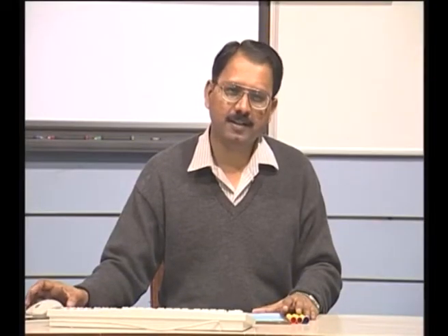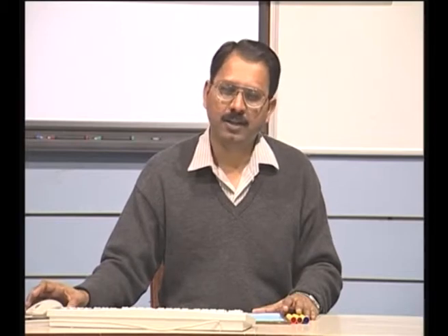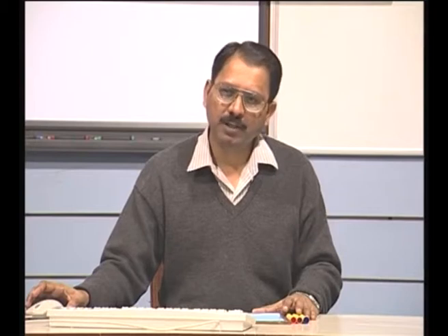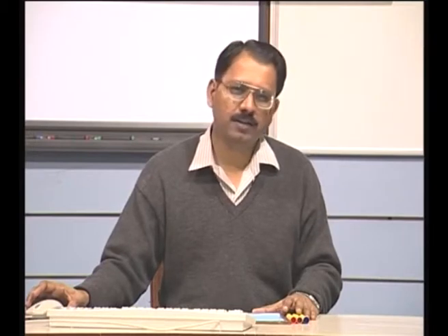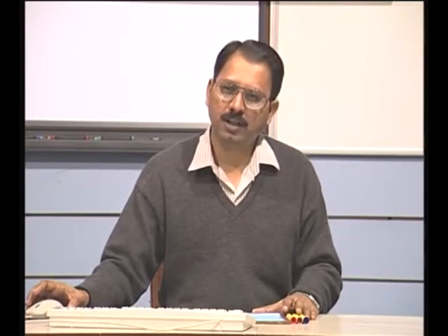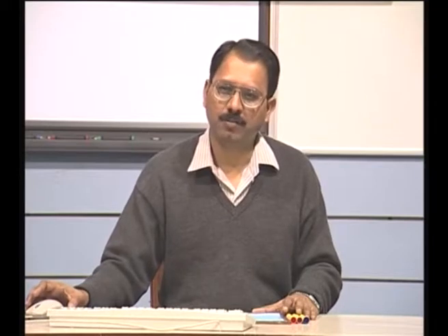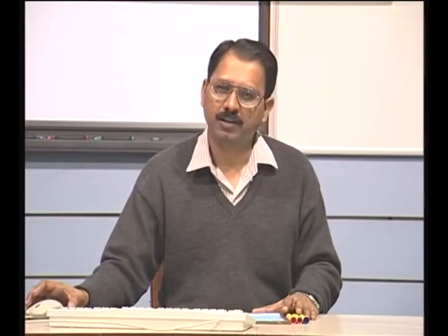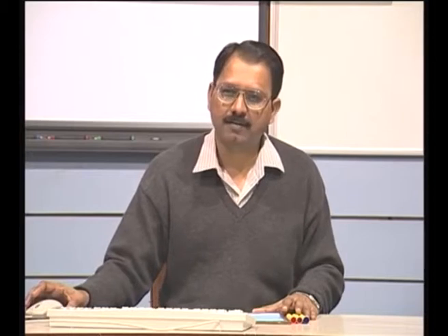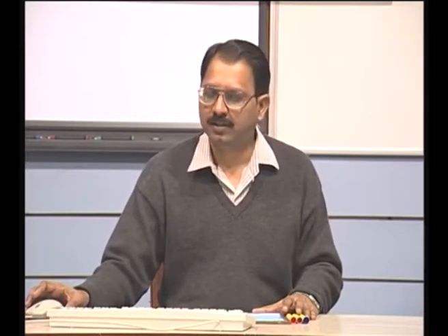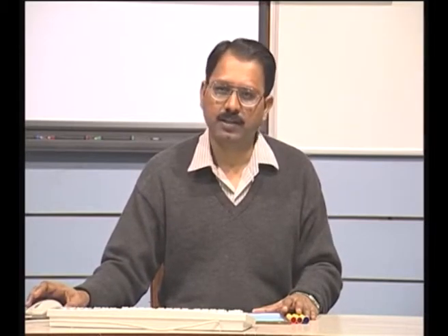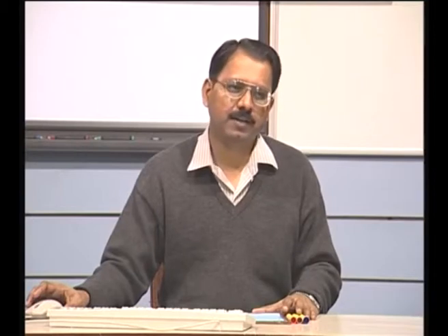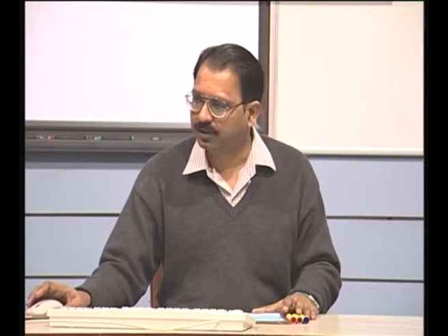So, the 16 that we have seen, you have terms like constant, you have u and w terms, u square, w square terms, u cube, w cube terms, then you have all the other combinations, u square w, u w square. If I take all combinations, then I have a total of 16 terms, and for x, y, z a total of 48 algebraic coefficients which can be used.